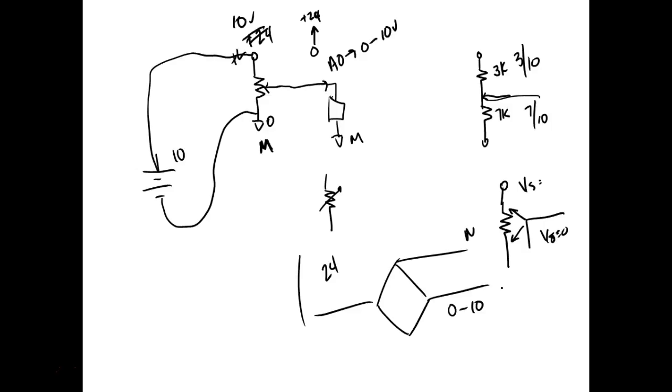So there are PLCs out there that are rated on 240 volts AC. But their inputs are probably going to be DC inputs, right? You understand? So they'll have a power supply built into them. Our PLC has a power supply built into it. The Siemens over there, the RSLogix over there, doesn't have a power supply built into it, so we have to run an external power supply.